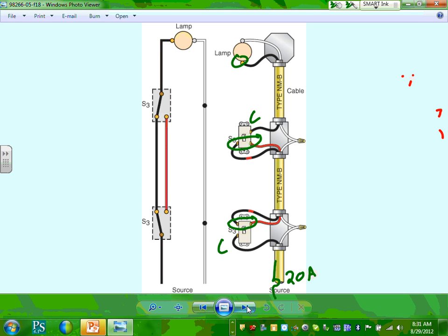Three-way switches. Again, we're designers, but the worst thing that could happen to you, Kerry, is you go to a job and you don't know how a three-way and four-way switch is wired. There's no reason for that. You have to re-identify that black traveler as red? You don't, but it's a good idea. That re-identification is just to identify in a workmanlike manner. It's good because now I know that these are travelers for troubleshooting.